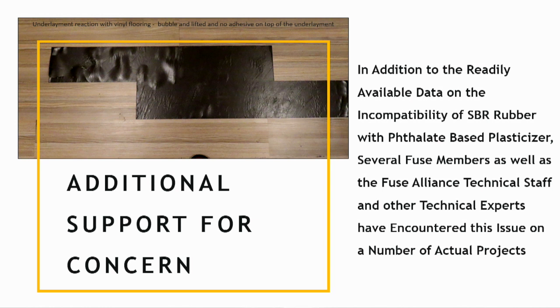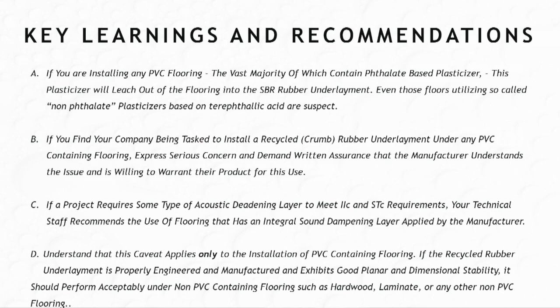If you do run into this, we want to talk about what do you do. Now, you're installing any PVC floor, the vast majority of which contains phthalate-based plasticizer. This plasticizer, it will leach out of the flooring into whatever you put it on top of.